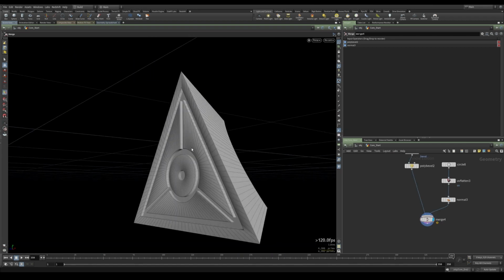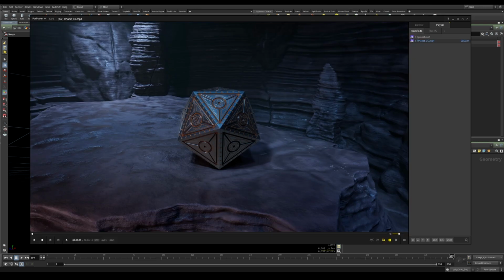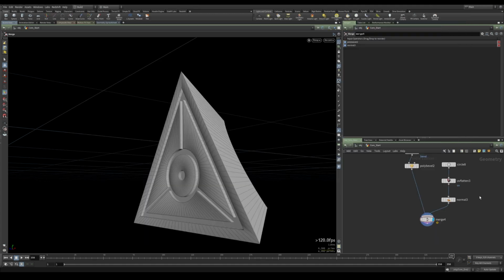Now this is the mesh that we are going to take into Substance, and we are going to create the material on a single piece and then reuse that material for every other piece. Because given the nature of an icosahedron, you will never see two faces oriented the same way, and given that they're sharing the material, it won't be noticeable. But before taking this mesh into Substance, we actually need to adjust some things.